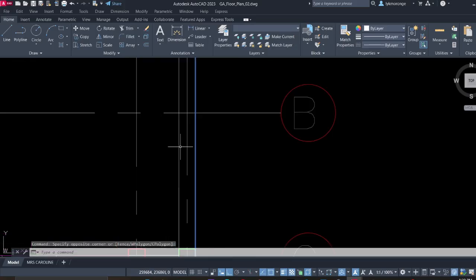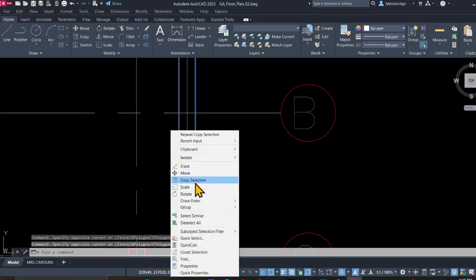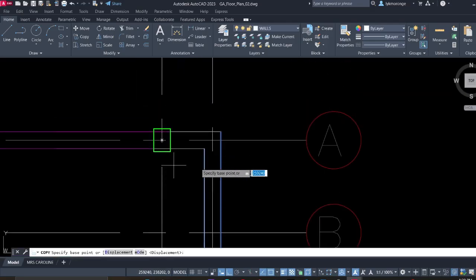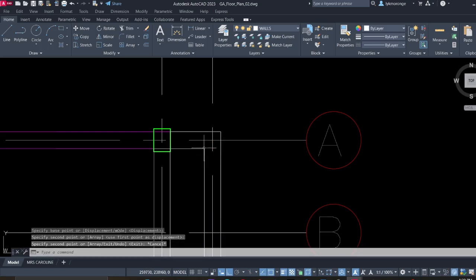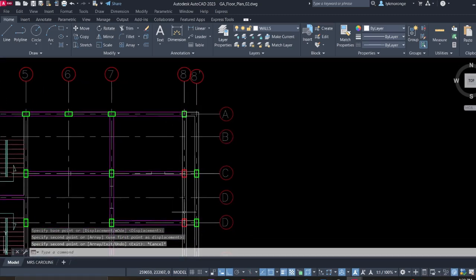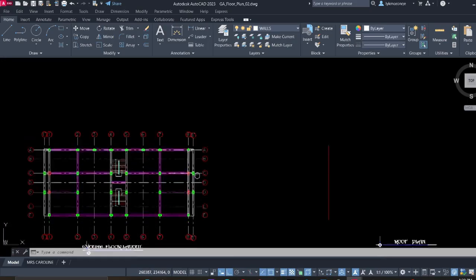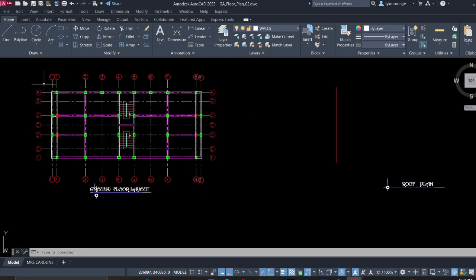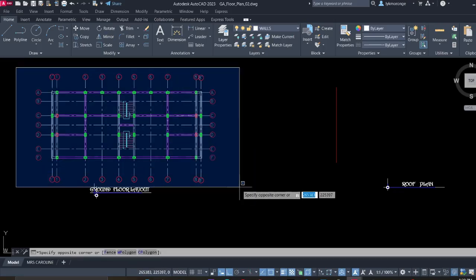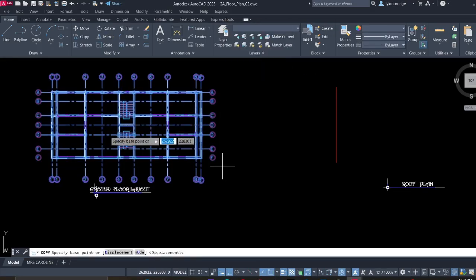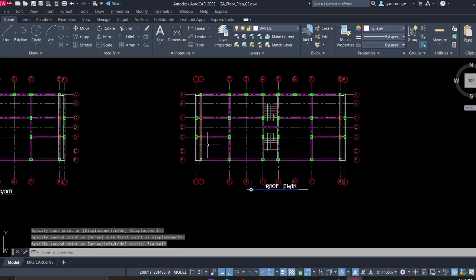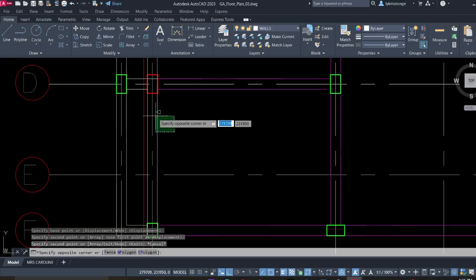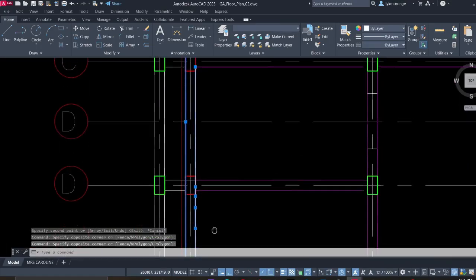But we can also have maybe a beam on top here, just to ensure that they hold these beams together properly. So our walls will run with this wall, but this one is just to ensure that these columns are well fixed or well formed. Just a smaller beam as compared to this exterior one. Just see that when you come to the roof, right click, copy, just copy this and move it a bit. Yeah, and once we are here now, actually we will not need this roof one, as I can just say here.